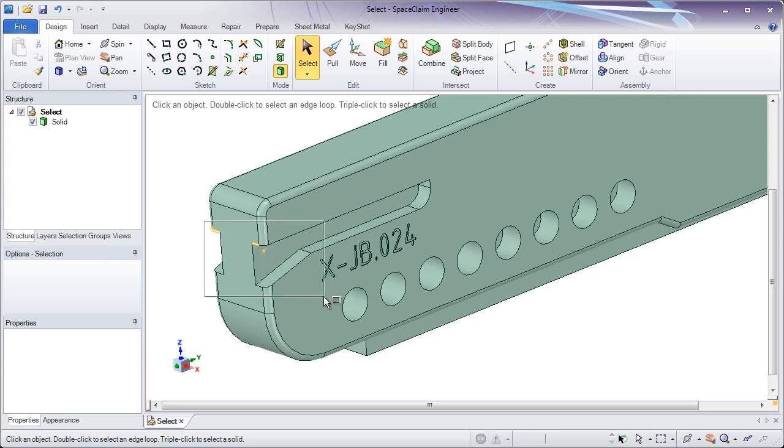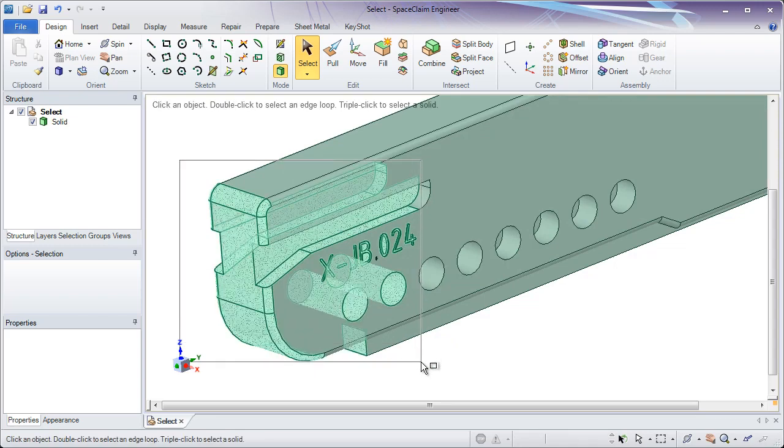As soon as faces enter my box, faces begin to be selected. If you like to control this, you can look at our selection filter on the bottom right-hand corner of the screen to get exactly what you need. Most of the time you'll want to box select from left to right, as I'm doing here, and pause to see what's in your selection.